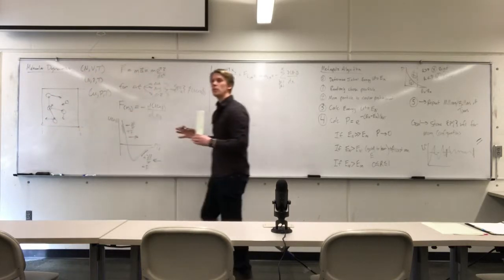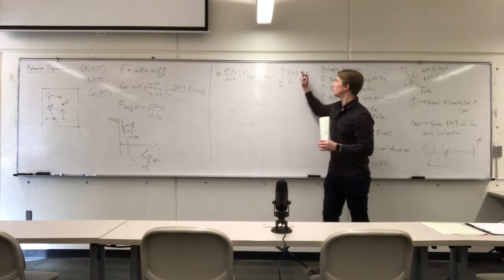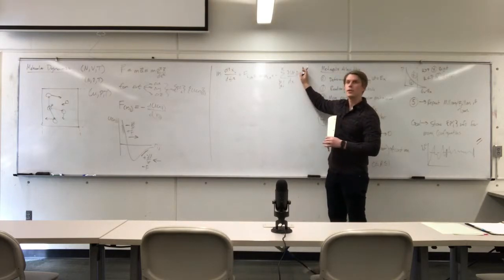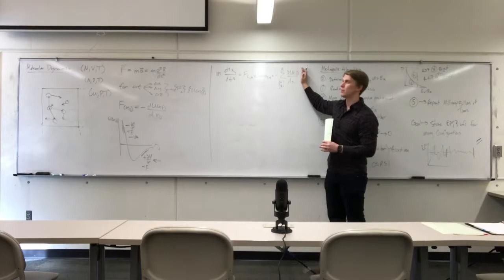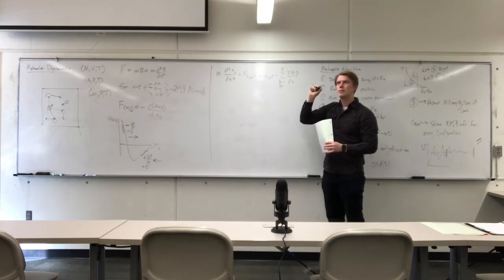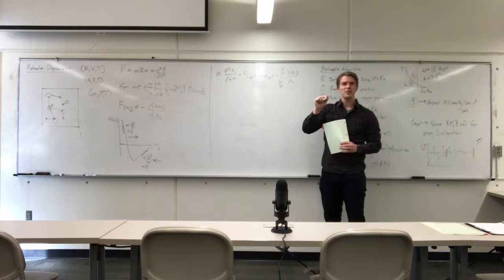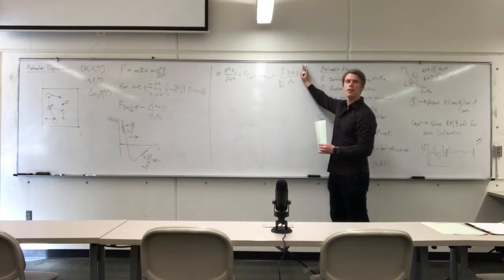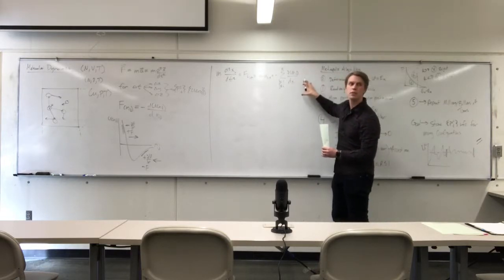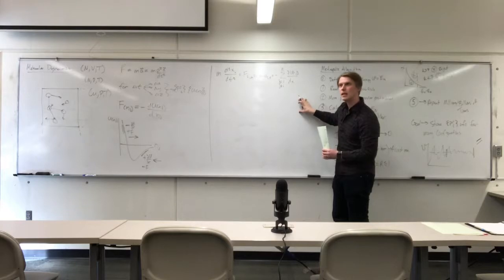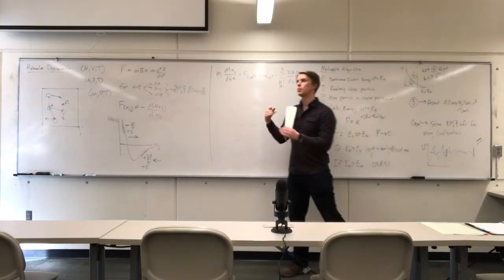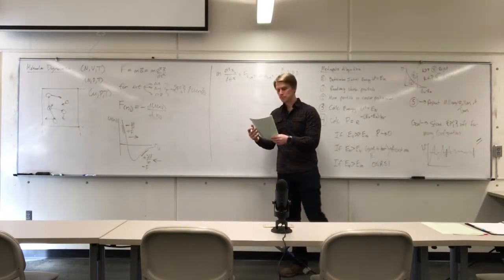Now, practically speaking, for really large systems, we don't sum up for everything. Otherwise, your simulation time increases, I think, to the power of n. If you add more particles, you're adding a lot of calculations, right? So you introduce a cutoff length. So you repeat this for x, you repeat this for y, you repeat this for z, and then you calculate the displacement for every time step.